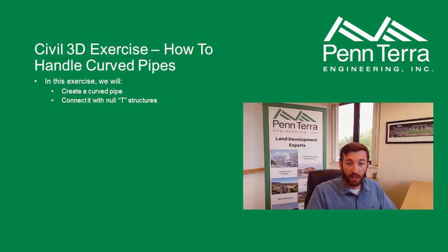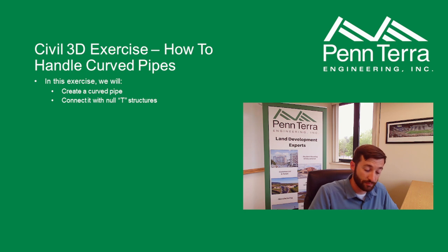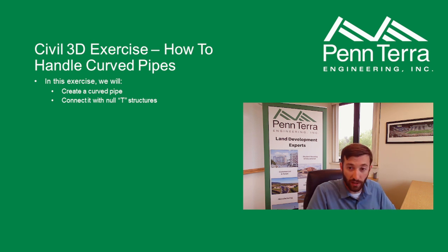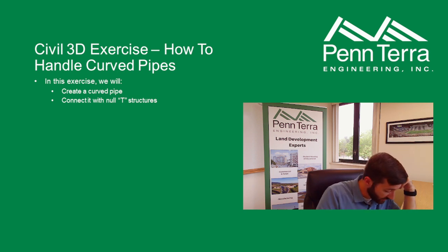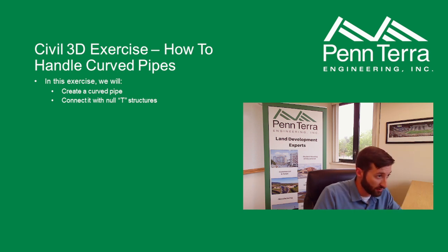Next up, I've had people asking about what to do if you have curved pipes. This often comes up on subdivisions where you have curves in the road. Generally, we hold an offset from the curb line with where these pipes need to be, so they're going to show up as curves. You can model that, but there are a couple of extra steps, so I'm going to show you how to do that real quick. So we're going to jump into a new drawing.